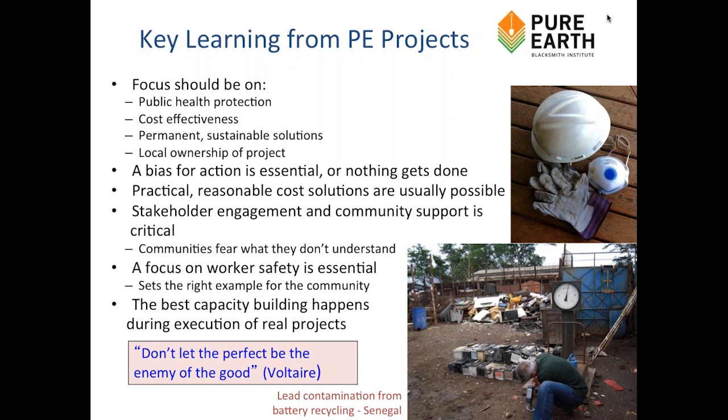So what I've generally done, for example, the Zamfara project, where the soil contamination was very extensive, but their standard was fairly low, we removed all the high contamination material. We actually set the number at 800 milligrams per kilogram to an offsite, to a nearby encapsulation facility, and then covered the other material, and then explained that to the government. Said this is meeting your standard because the soil that people will be exposed to will be below a very low standard.